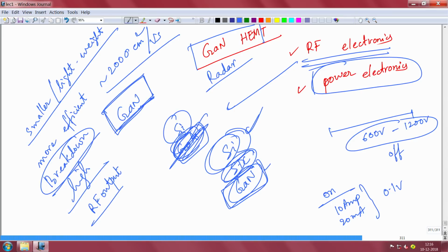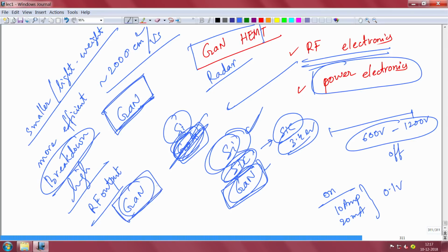Of course, there are other technologies like silicon carbide, which is also a compound semiconductor technology. Its band gap is 3.4 eV, exactly that of gallium nitride. But gallium nitride has more material property problems. Freestanding gallium nitride substrates, like silicon wafers you can buy, are not readily available. A pure GaN wafer is difficult to grow, so it's very expensive, and you cannot make large scale devices for commercialization. So you grow gallium nitride on something very cheap, mostly silicon for these power devices, and this makes it very cheap.